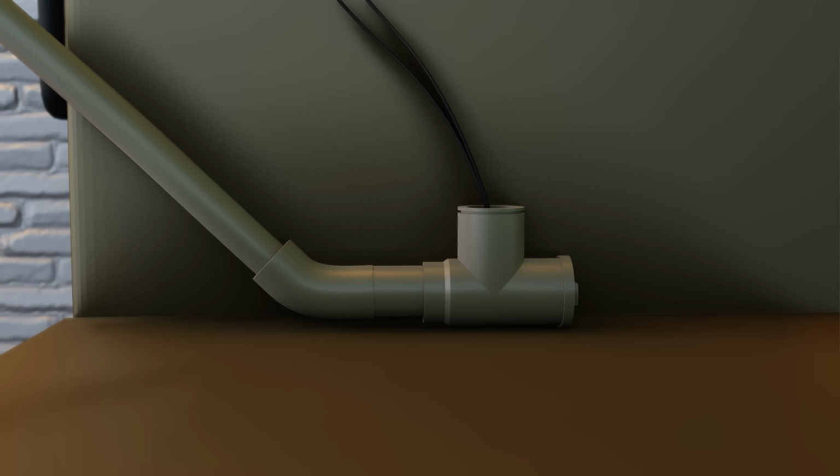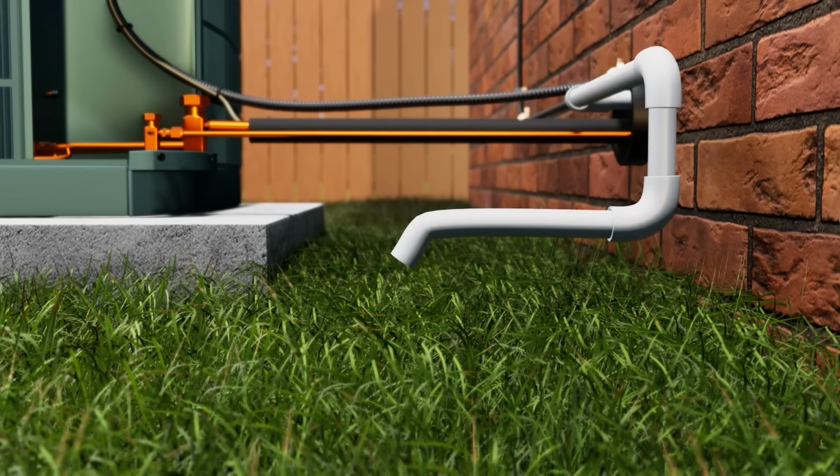Let's take a quick look at the condensate drain. The condensate drain has to be trapped and vented and pitched outside. In some cases, you won't have a vent like this. In Florida, it's very common that these drains will just run underground and then outside. It's not ideal, but it is the way that often they are set up. But it will still drain outside, even if it goes down and back up, because of the weight of the water, or the column of the water, that's pushing it out.